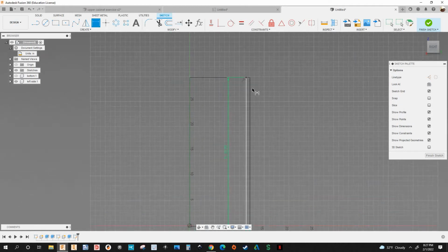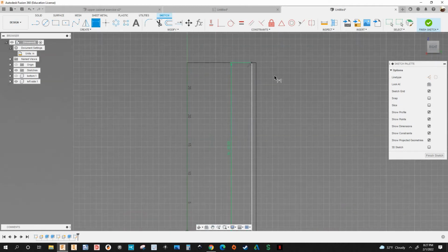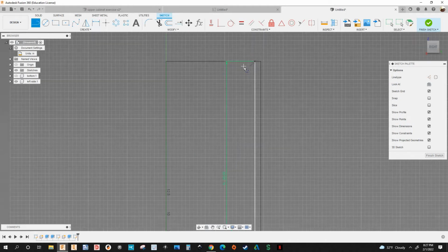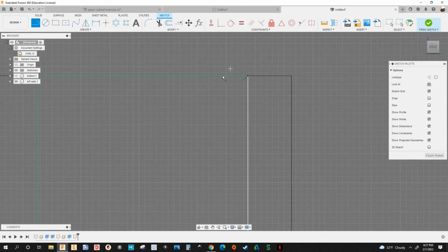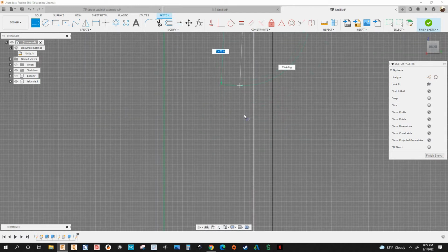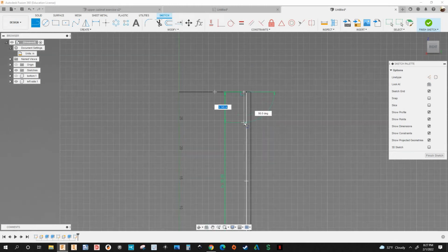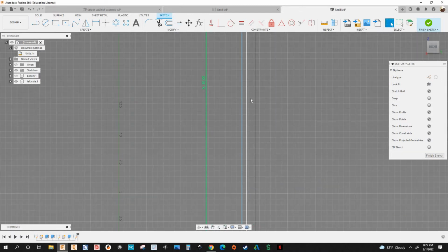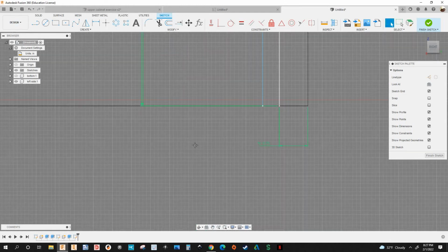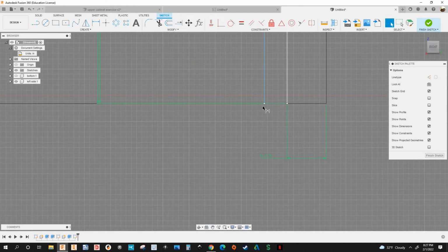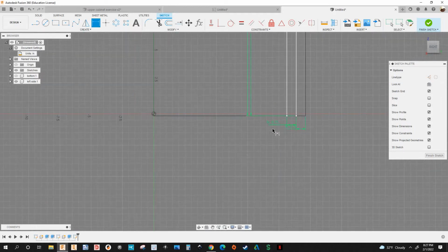Now I'm gonna create that groove for that back panel. Okay. So I'm gonna hit L on my keyboard. I'm gonna snap it right there. Go down. Then I wanna type side height. Hit enter. Okay. Now when I hit D on my keyboard for dimension, select that point and that point, and I'm gonna type thickness. Hit enter. Okay.